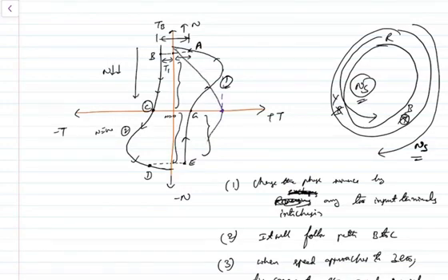So this will be my negative direction. This is my curve number 1 dash. Whenever you apply plugging, it is passing like this, and let us assume it stabilizes at some point. Corresponding to the required value of the load torque, it will stabilize at some speed. This much torque is required for your load, so at this point is the original speed. Whenever the speed is changed, it will reverse, and again this same characteristic will come in the opposite direction. So here this will be the opposite direction curve.